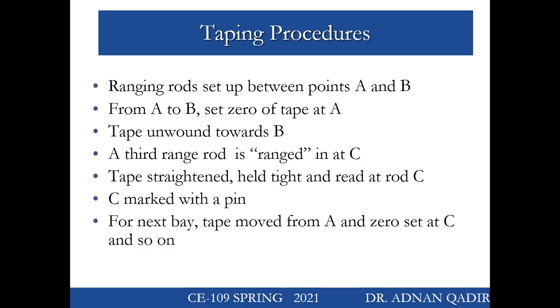But there is another way I can tell you, maybe not here. Whenever you set the rod at A and set the rod at C, what you need to do is take a string that is obviously longer than the distance you measured.